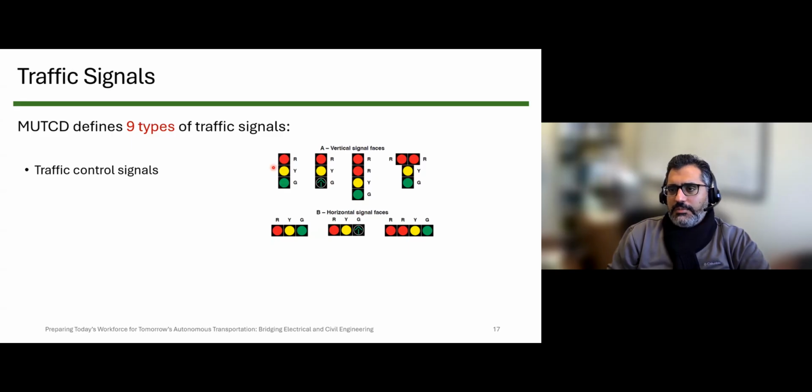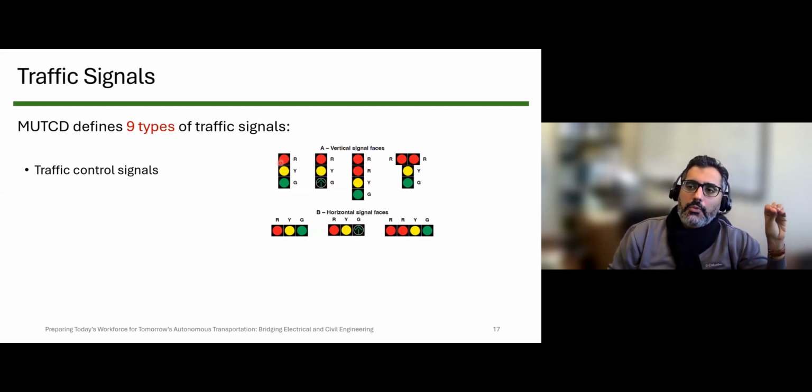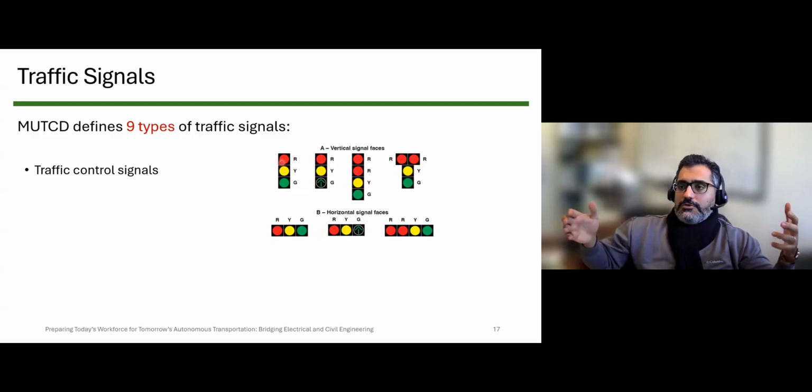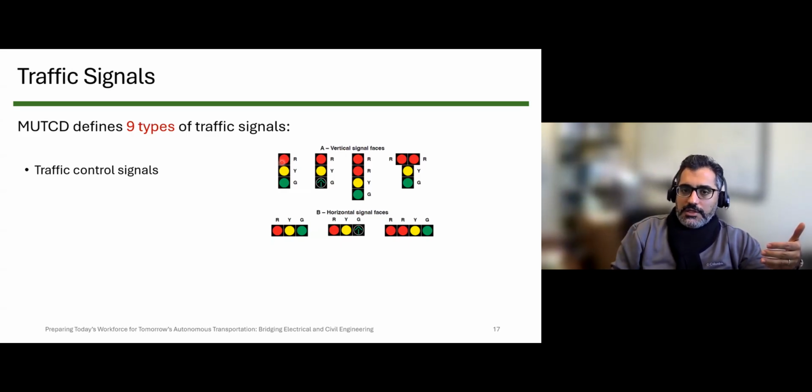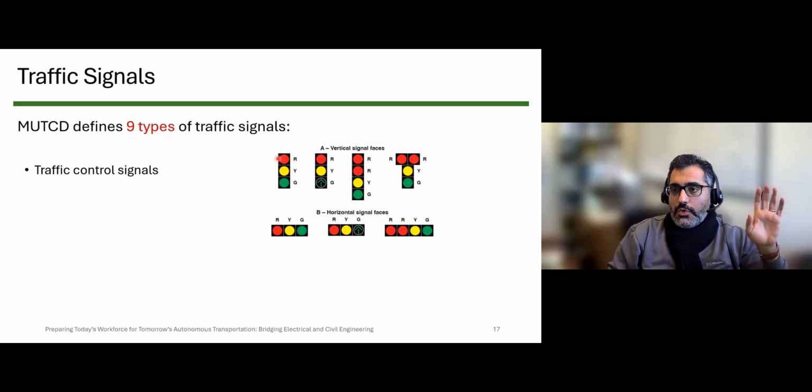But just for your information, going back to the messages, remember that we had these 3 colors. Every one of them is conveying a message. Red is prohibition, is a stop. Yellow is warning. Green is allowed movement. Now, in this setting, which one goes on top? Red goes on top. Why? Because that is the most important message to be transferred. So if there is a truck in front of you, we want to make sure that the one that has the best visibility for drivers is this red indication. That is why red is going to be always on top.